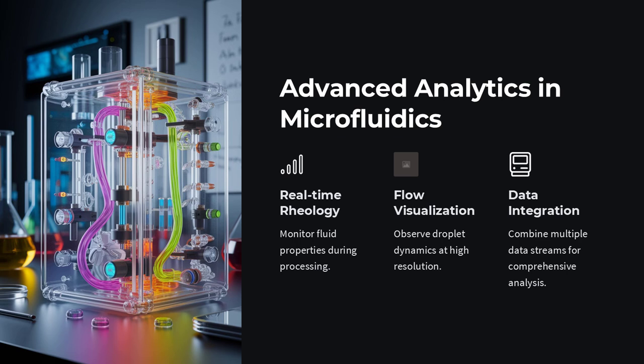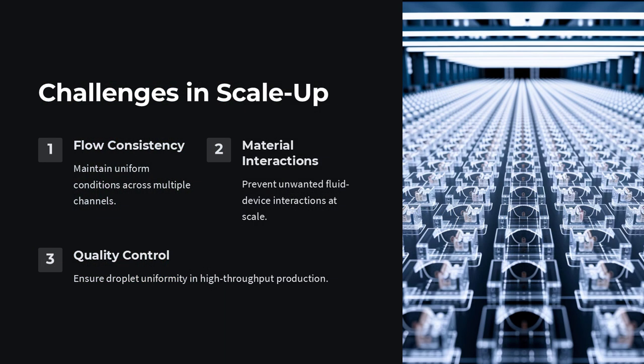Emerging technologies continue to push the boundaries of what is possible with non-Newtonian fluids in microfluidics. Advanced analytical tools such as high-speed cameras, micro-PIV, and in-situ rheometers provide unprecedented insights into the local flow fields and stress distributions within microchannels. These tools allow researchers to correlate specific rheological properties with droplet formation dynamics, enabling the development of predictive models that can guide the design of more efficient devices.